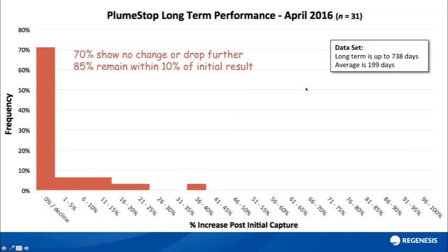This is significant. When we conduct a pilot test, the whole purpose of a pilot test is to calibrate the main dose that we'd need on a site. If we put an excessive amount of PlumeStop to guarantee a result, that's great for getting a good result, but it tells us nothing about whether we were exactly on dose or only just on dose or not quite on dose to get the maximum balance of dose response. So pilot tests are typically designed to be injected right on the balance of what we think is about right, so that we can then see how much more we might need to increase the dose or reduce the dose, whatever it may be for the pilot application.